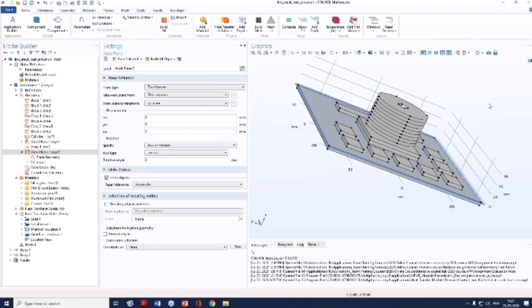How is the rotate feature different from the revolve feature? Well, with the rotate feature you will be rotating one geometric entity and creating, let's say, a circular array or so. Whereas with the revolve feature, you will be revolving a surface around the axis of rotation. Normally the revolve feature is used to create a 3D object from the 2D cross-sectional area, whereas the rotate operation is typically used to create multiple copies at different angles, like creating a circular array of the required object.